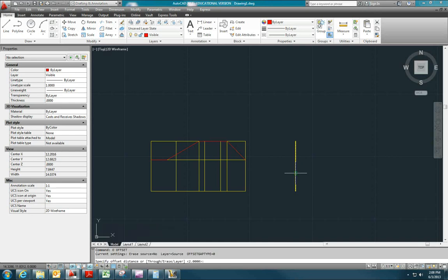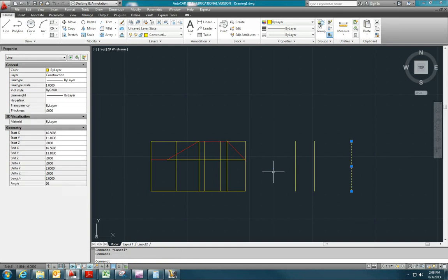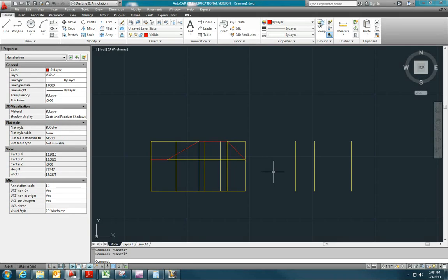So let me do some offsets. O, enter, 0.76, enter, and I will offset that back. And then let me offset this front edge by 2.24. Again, I'm looking at dimensions given in the text. And I will offset this line back toward the front by 0.76. Now I know that the very top surface of the object up here is 0.5 wide, so let me offset for that.